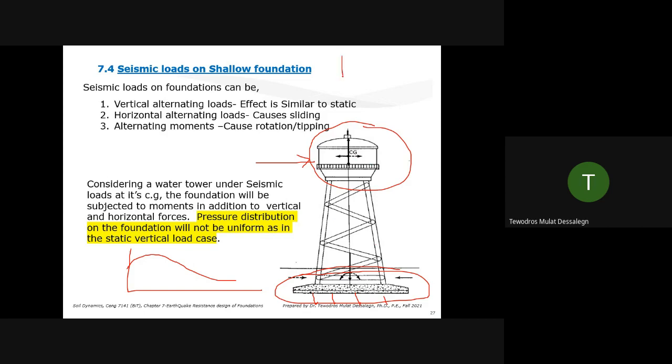That is the most significant period, because the mode of vibration may be more complicated, maybe like this. Usually we focus on the first mode, which we call the fundamental mode. The peak of the fundamental mode is here. For the rest, what did we do last time, to account for other modes, other peaks?